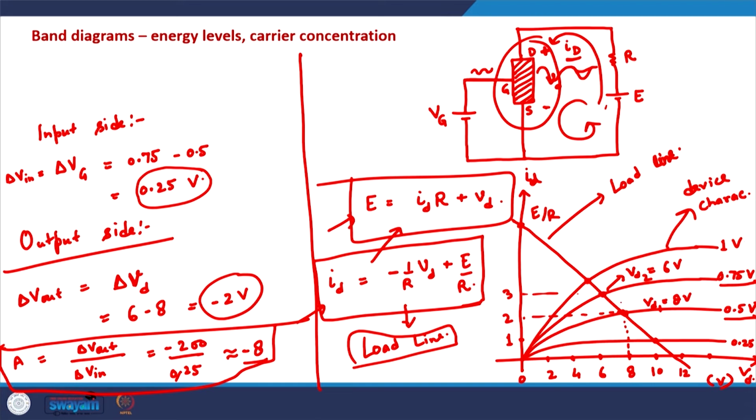And obviously proper DC biasing conditions need to be maintained. So, in this amplification no energy is getting produced out of 0. So, it is not as if we are able to produce a large signal out of a small signal, it is not that, because we need to maintain the proper DC biasing conditions. So, there is a net loss of energy, but a small AC signal can be converted into a large AC signal, and that is how the amplification can be achieved in the MOSFETs.